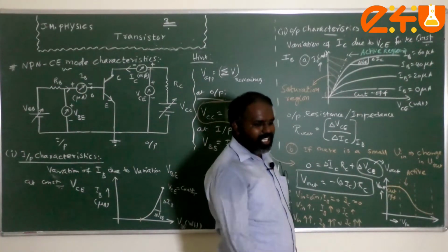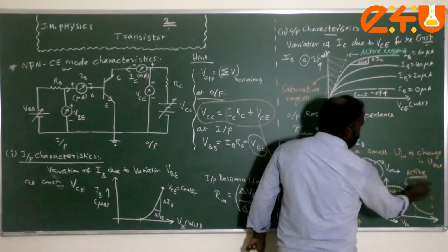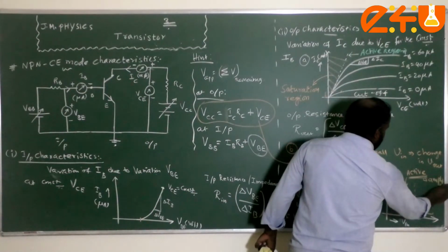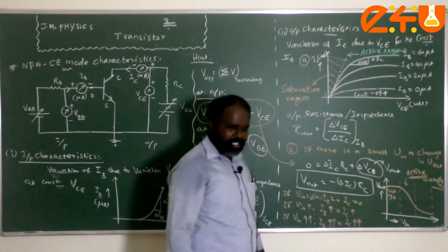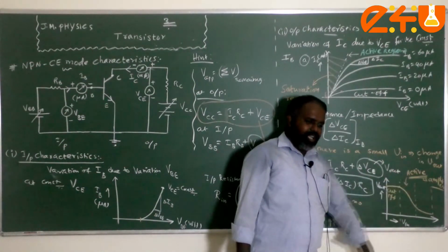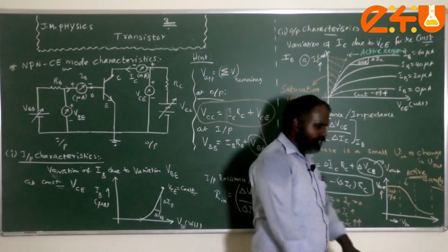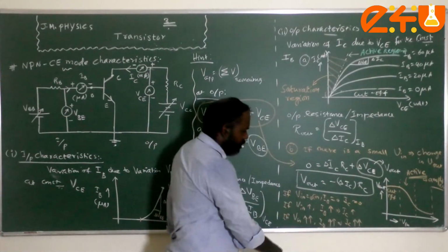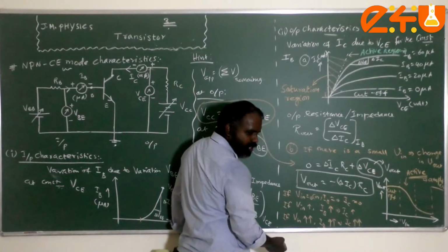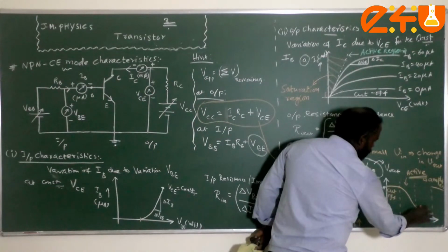For the transistor as an amplifier, this region is used in the amplifier circuit. That means we have to maintain our transistor within this condition in order to use it as an amplifier. But when Vin is maximum, for example more than 1 volt, then as we said here, when IB reaches the maximum, there is a corresponding maximum output current, and it will decrease the output voltage.